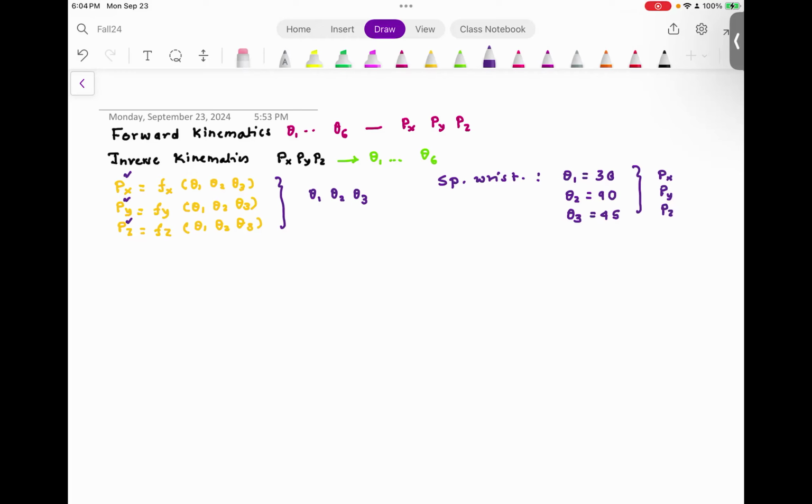So if you have this condition, theta 2 equal to 90 degrees, theta 1 and theta 3 as 45 and 30 degrees, you can get some px, py, pz. But when you try to plug this px, this py, and this pz into your inverse kinematic solver, it will not work. That is one practical way you can verify that you have a gimbal lock.